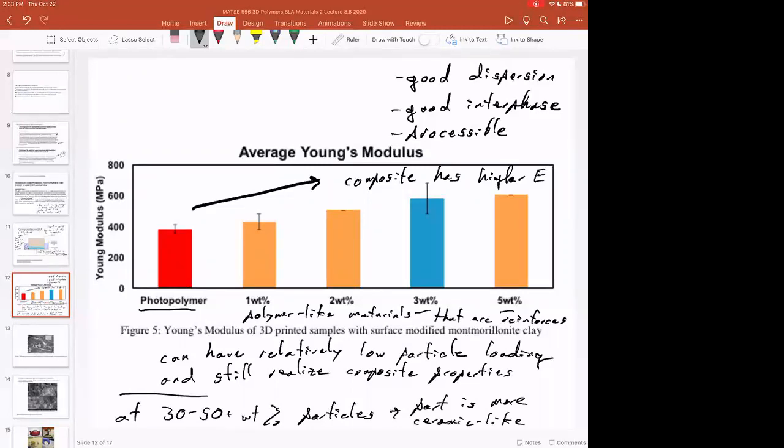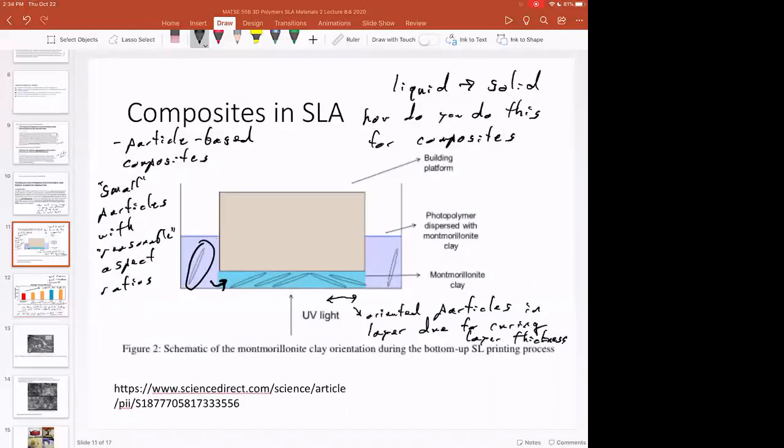So it has higher surface hardness, it's more brittle, it probably has a higher Young's modulus depending on how it's designed. And so now again, just varying the recipe or varying the polymer to filler ratio, you can get parts that feel different and have much different properties.